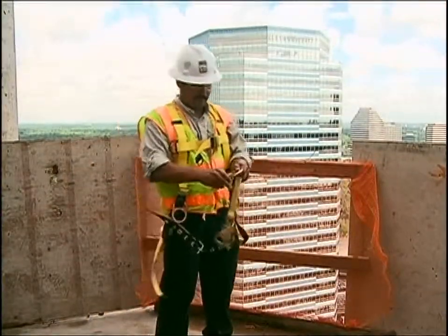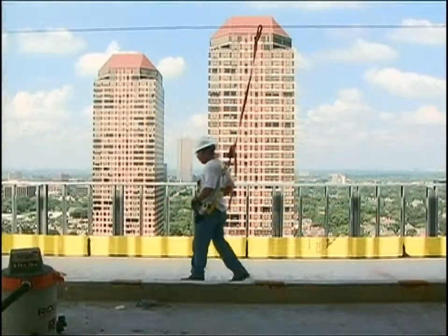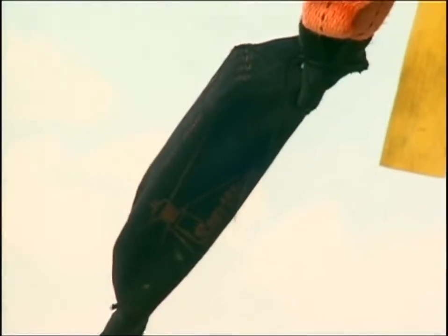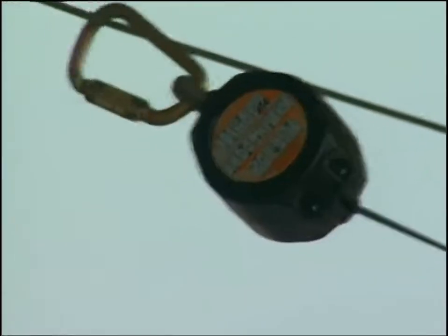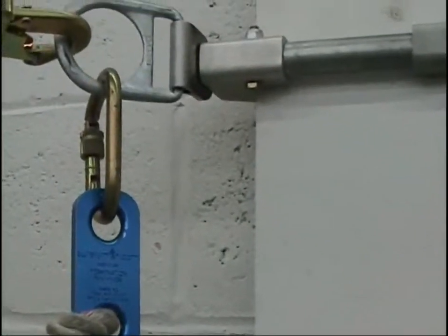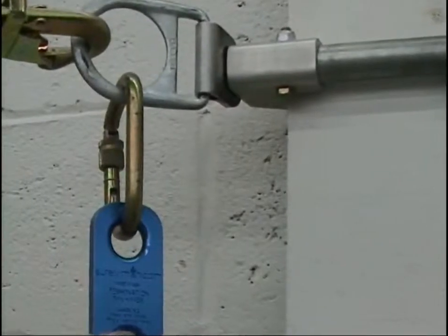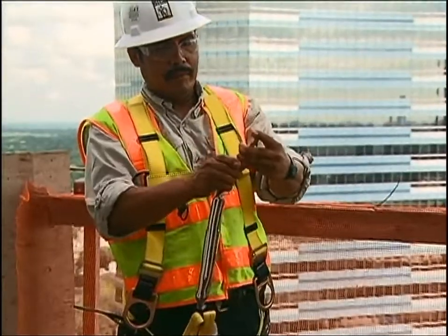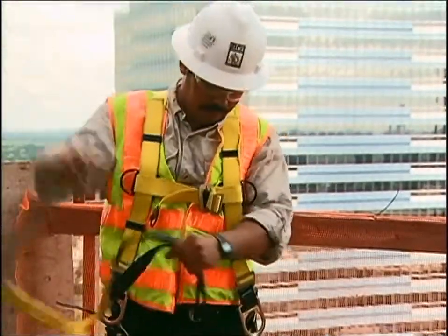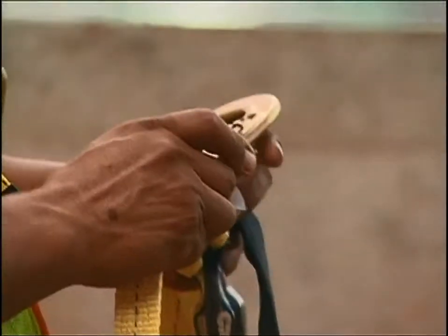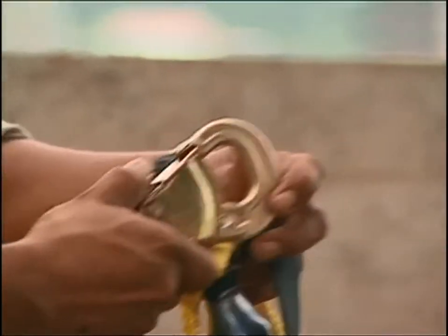A personal fall arrest system consists of a full body harness designed specifically according to the workplace application, a shock-absorbing lanyard or self-retracting lifeline designed to take the strain out of a fall, and an anchorage, a secure point of attachment for lifelines, lanyards, or deceleration devices. Your employer will select personal fall arrest systems appropriate for the type of work being performed. Choosing the right component in each category is critical to safe functioning of the system and protection of the worker.